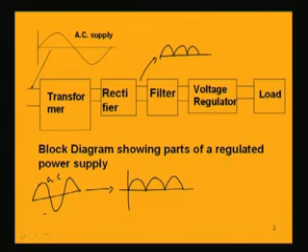So what is done here, as we have earlier discussed, we use a filter circuit having a resistor capacitor. We use a filter circuit, and from this filter circuit we get the output as a voltage which is having this type of form. That means it is having ripples, no doubt, but it is in a better form than this pulsating DC.